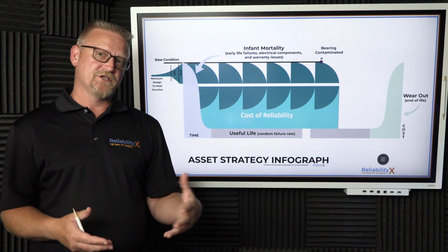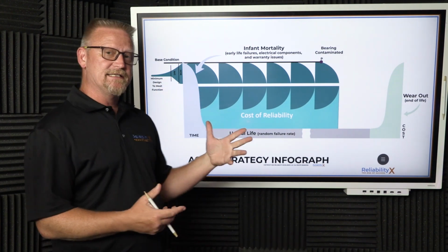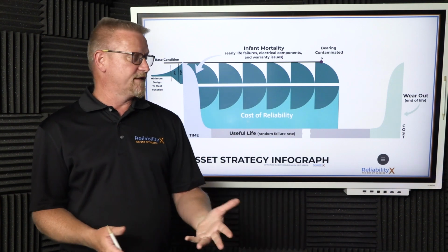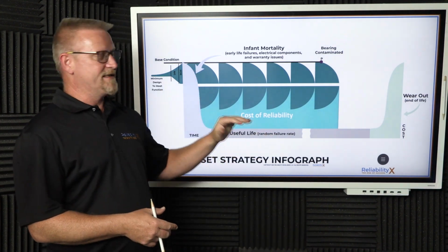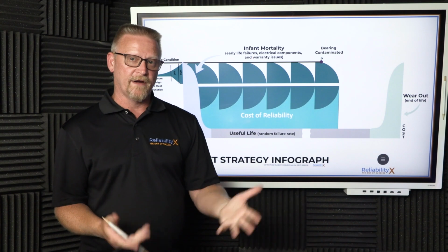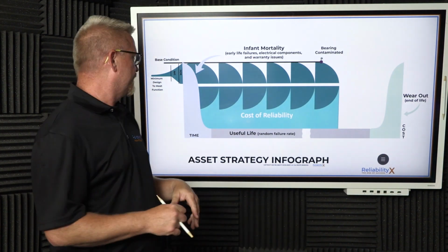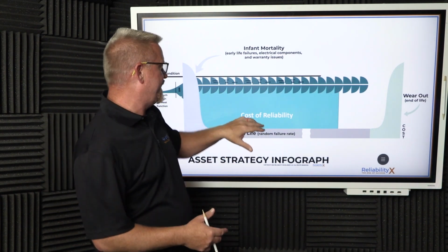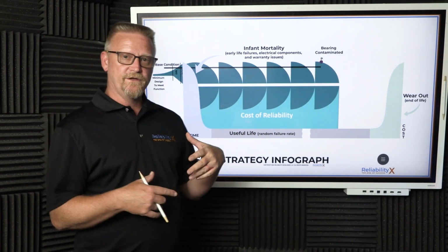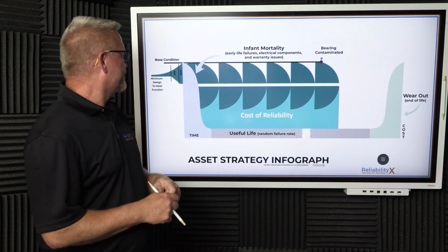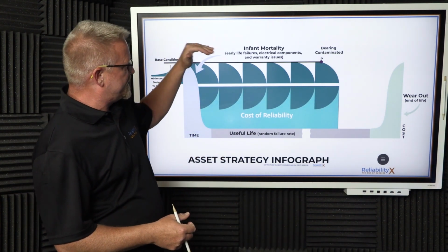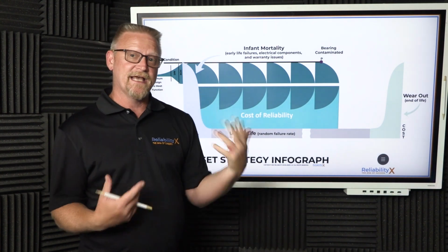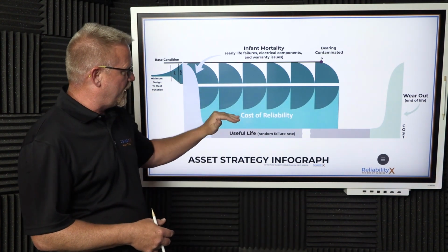When our base condition is improved and we use techniques where we are identifying failure modes and the use of things like predictive technologies, what happens is we deteriorate at a lower rate when we design it better using design for reliability. And our costs are lower because we're using better techniques when we use an approach like RCM. So we deteriorate less over time, less often, have to take fewer interventions, and our cost base is lower.